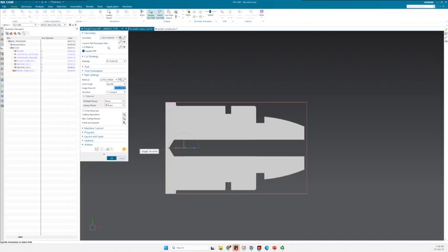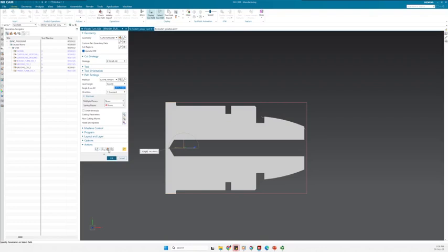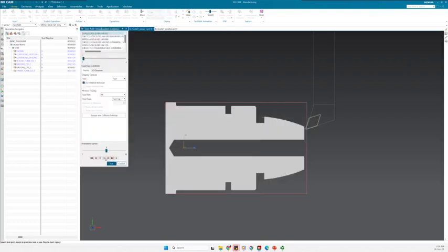And then what I will do is that first maybe I can just generate and see if there are some problems happening. So verify, and then I can see that now there is something, and then it stops. Of course, it stops because it now only understands this member to finish it. But now I have 2, 3 members. So what I need to do is define multiple machining region.